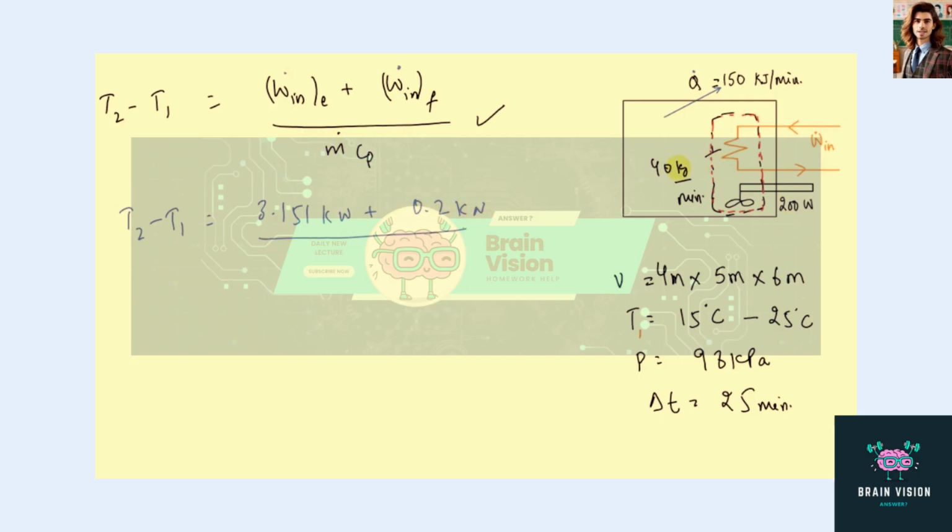Now m dot is given in the question as 40 kg per minute, but we'll be converting it into kg per second, so I'm dividing it by 60. So this many kg per second times Cp. Now Cp for air, we know, is 1.005 kilojoule per kg Kelvin. So from here we'll get the answer as nearly 5 degrees Celsius.